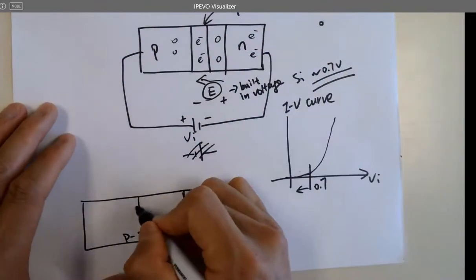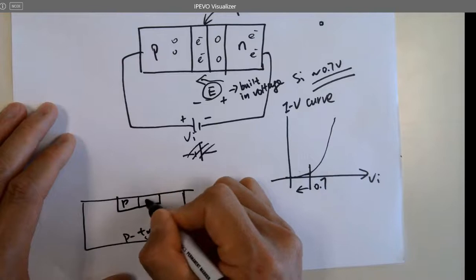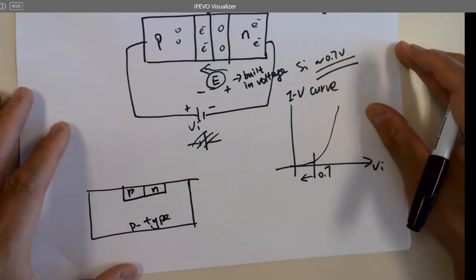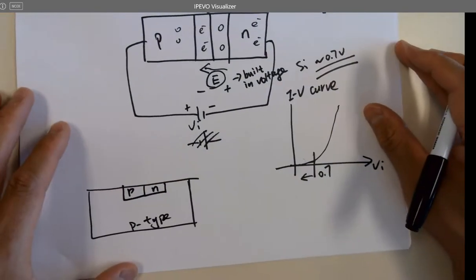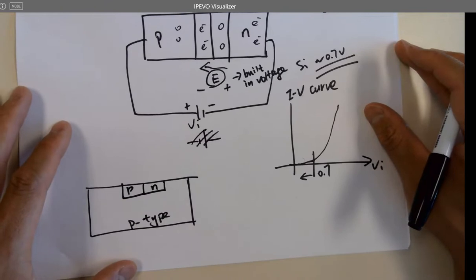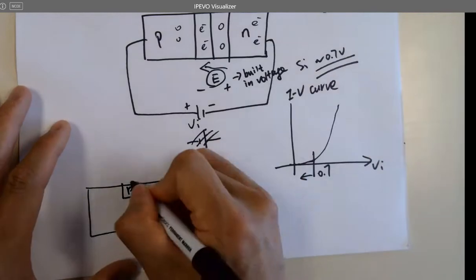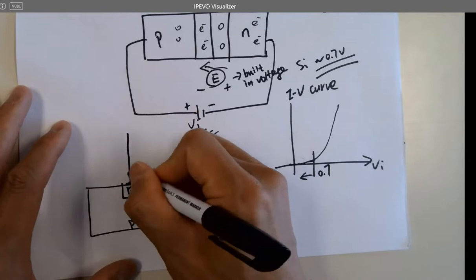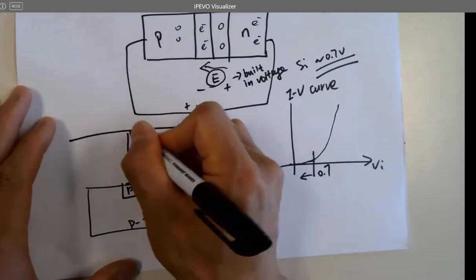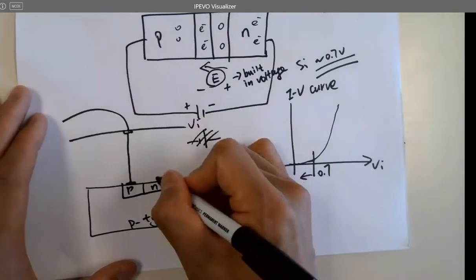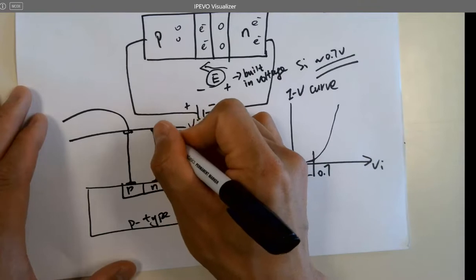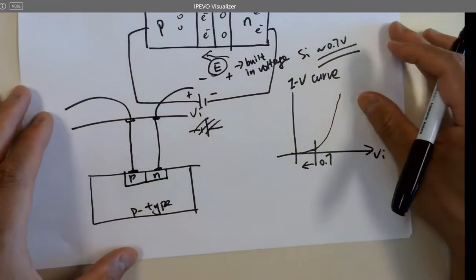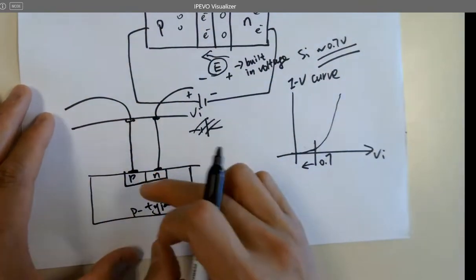You're thinking, hey, P, N, is this going to work or not? Why? Because it's majority P-type on the outside. And then you've got a connector, and make a wire, go through metal 1, metal 2, metal 3 until the very top layer has an opening, and wire bond it. We just do it that way.